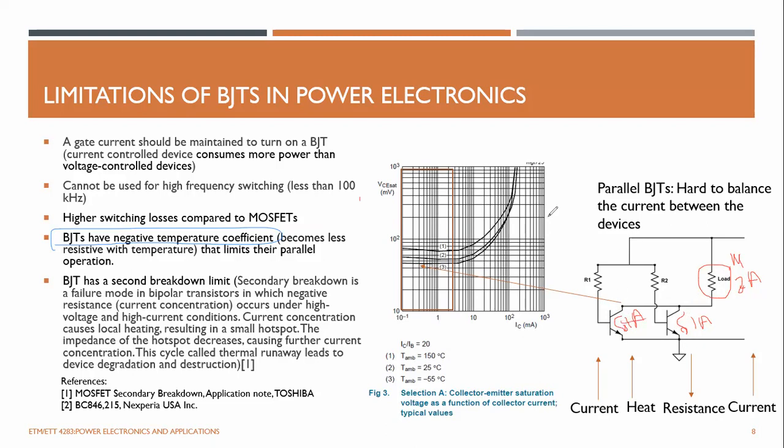Okay, so that's the purpose. You just need to double the load current. So this is your biasing circuit. It doesn't need to be connected to the supply. It could be connected to your controller. These are the base emitter biasing resistors. This is your control signal, and this is your load, right?